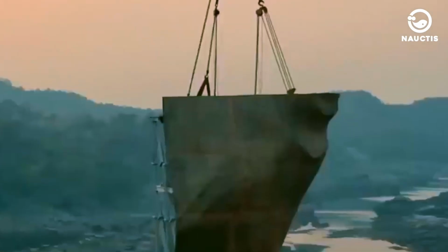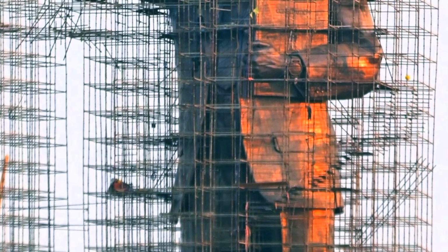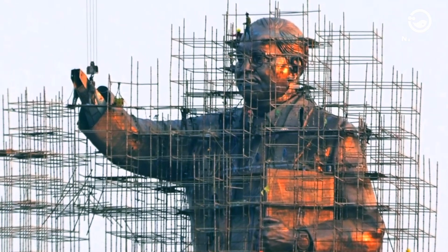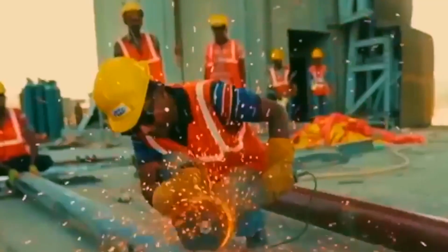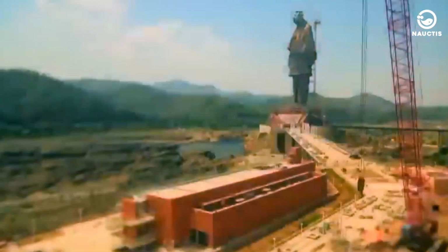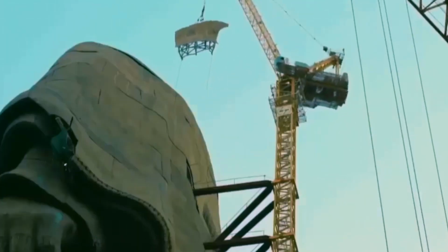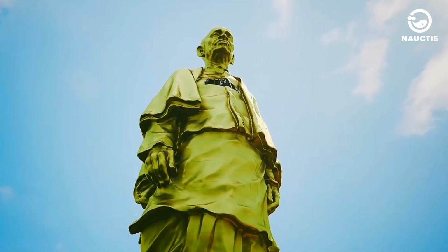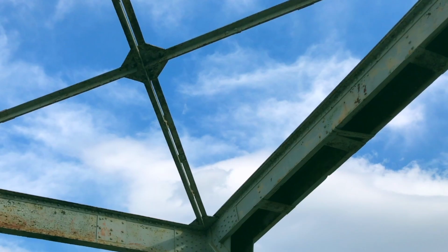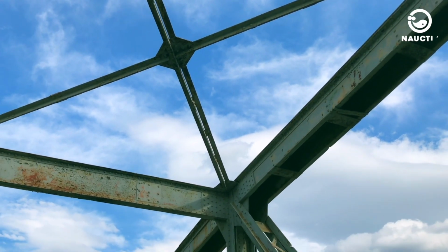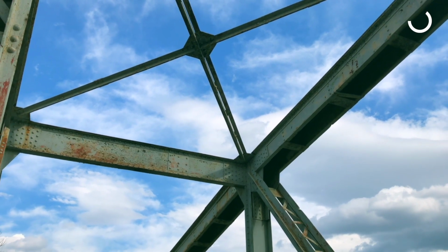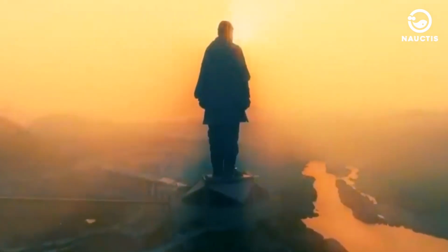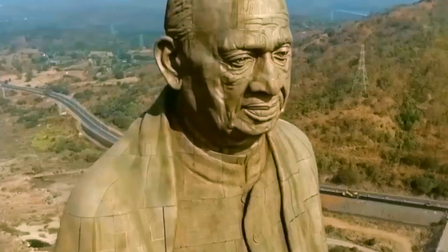The construction sequence is as follows. The hill's fracture plane was treated through grout injection and grouted anchor rods. Then the hill was compacted to build the mat foundation. After that, the raft foundation was cast. Then W360 shaped structural steel was embedded in the composite core wall. The W360 shaped structural steel was then connected with internal clamps of 150 mm by 150 mm angle. After the structural steel was erected 16 to 33 feet above the foundation, the core casting process began.